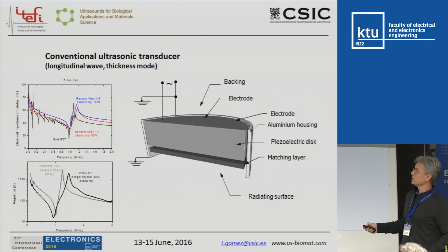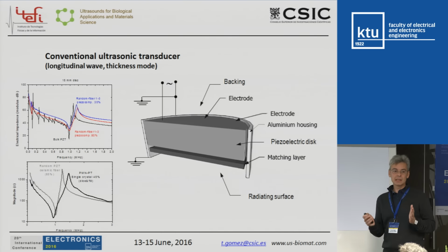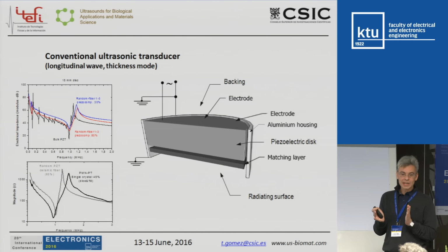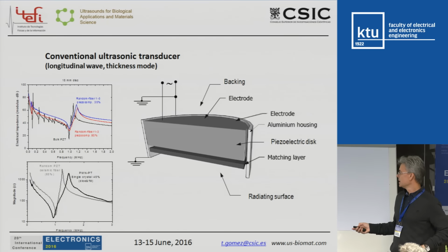You can increase the bandwidth if you use a 1-3 ceramic composite, and you can increase it even more if you use a single crystal. This is a PMN-PT single crystal piezo composite, and the bandwidth is larger in this case. Anyway, you always have a physical limit defined by the piezoelectric material that you are using.